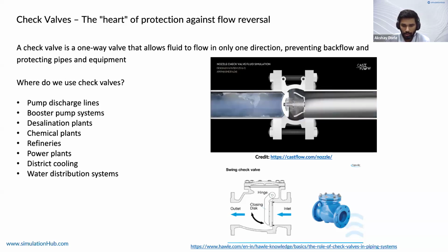We have booster pump systems which have multiple pumps running in parallel. So again, very important to have check valves in such systems. Desalination plants, refineries and chemical plants. Any process which has multi-stage equipment uses check valves very strategically. So in refineries and chemical plants, this becomes a very essential component.